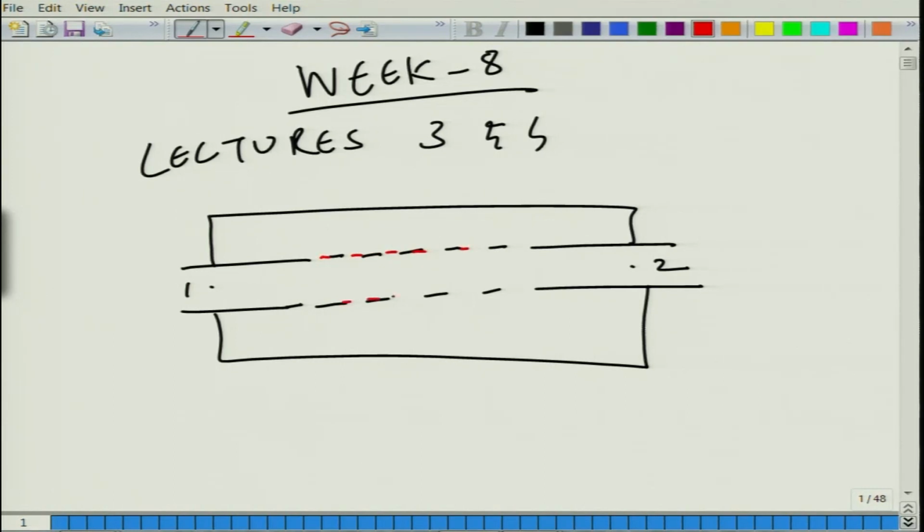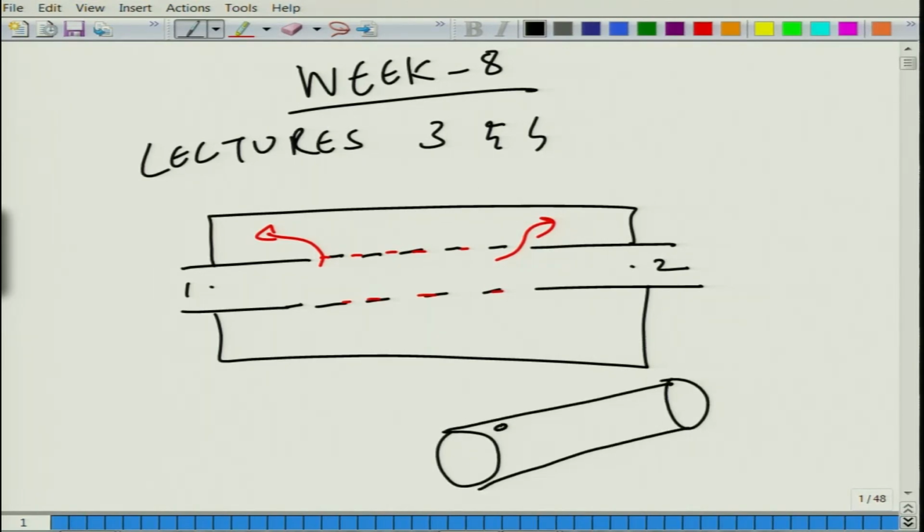So what does it really look like? What I have always been insisting is that it guides the flow, does not allow the flow to freely expand, and allows the waves to interact with the annular cavity and the neck extensions. So, basically here we have a sort of a pipe. So, this is perforates. What I am going to do now is show you some nice photographs of the perforates.